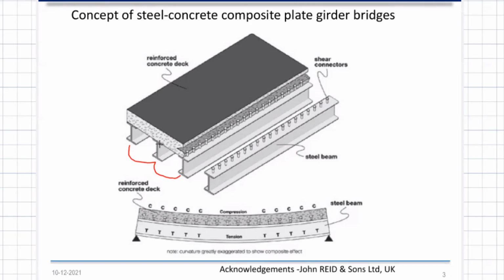Now, on top of it, I put concrete, right? We put concrete, and this is a bi-material system. I have steel and I have concrete on the top. Now, the modulus of the concrete, as you know, is less compared to the modulus of steel. Correct. Now, what happens if I apply a load on the deck? The load goes to the deck first. Now, depending upon how the deck and the beam are connected, a composite behavior occurs.